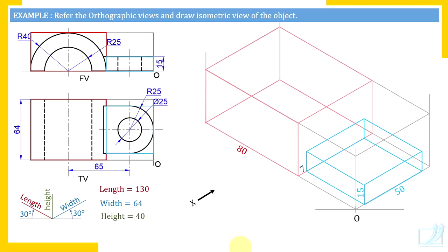This is major work. I say that 50% of the work is over because now it's simply to give shapes to the surfaces. So let's proceed. We are now going to give shape to this surface. What is shape of the surface? It is semicircular surface. So we'll have to draw these semicircular edges. If you don't know the 4 center method to draw isocircle, go through the video which I have already uploaded on isocircle. Be sure that you have understood procedure of drawing isocircle.